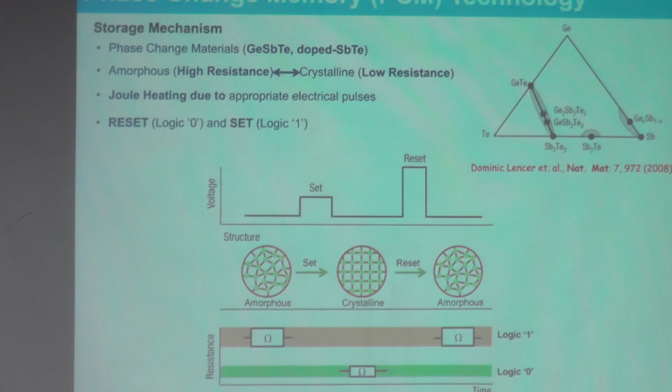There are multiple techniques available. PVD is a basic technique that is already there: thermal evaporator based techniques, sputtering units, and if you go to the higher side, ALD deposition is also there, and molecular beam epitaxy. Based on that you can coat these chalcogenides. Based on the appropriate composition, you can deposit these thin films, and then accordingly you can characterize. For deposition of these films, based on the elements, you can identify the suitable composition, and then you can deposit.